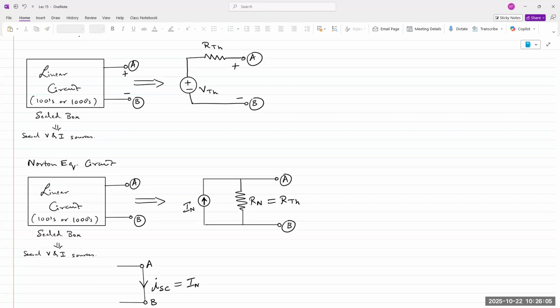So again, the setup of the circuit is important. The analysis is something you've already done. Once you place a wire between the terminals A and B, the circuit changes, and you analyze it using any method that you want: node voltage, mesh current, superposition. The current that you find in that pathway between A and B is your Norton current.